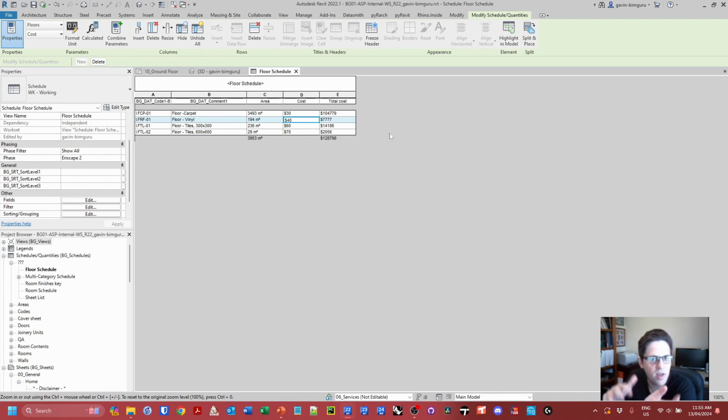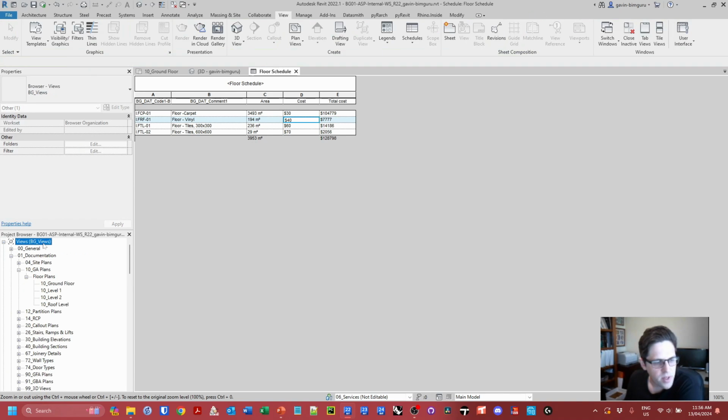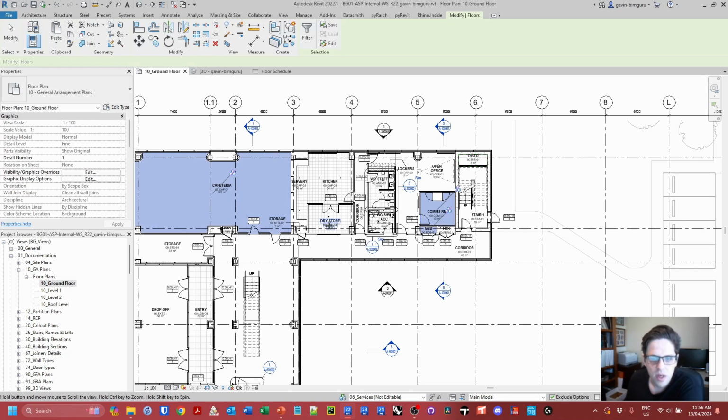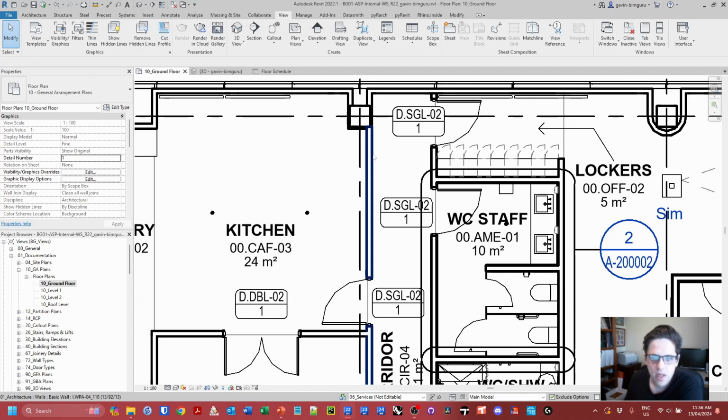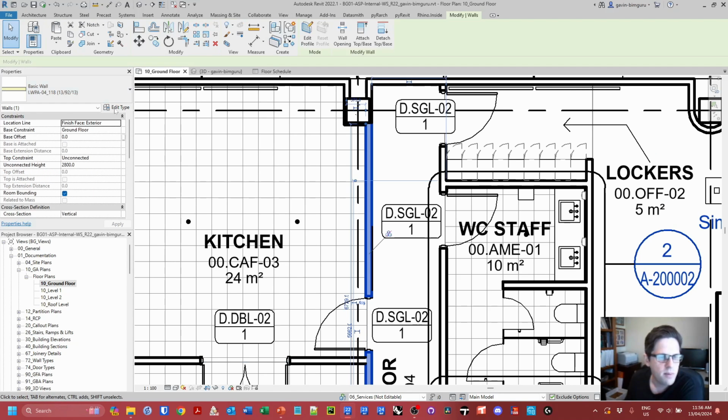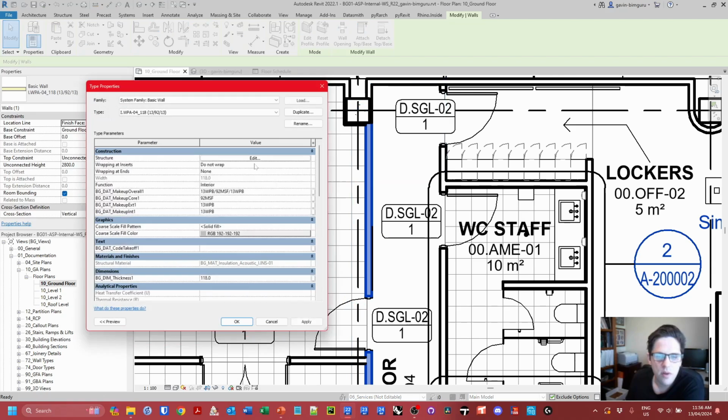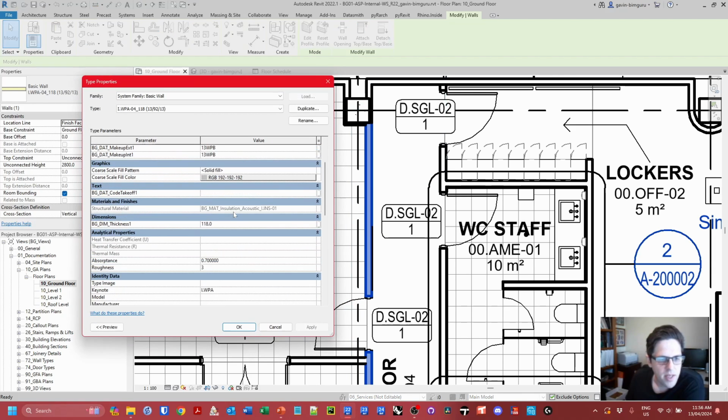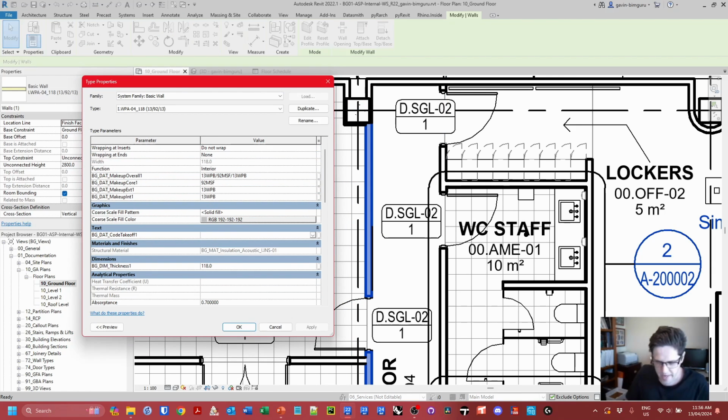If you have mixed mediums of cost takeoff, you will need to use something like Dynamo to bring them all together. I'll very quickly show you how you can form a query to get all the relevant elements in your model. Let's in this case say that we have something that we want to measure by a different rate. So let's, for example, say that I want to measure a wall by lineal meterage. Let's say in this case, this wall type, IWPA-04, is going to be measured instead under its cost takeoff by LM, or lineal meterage.